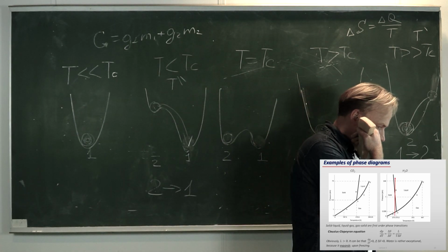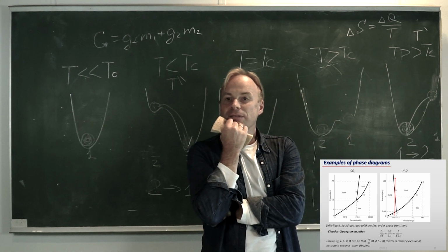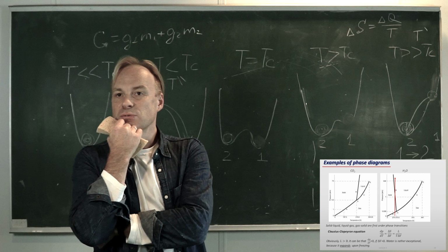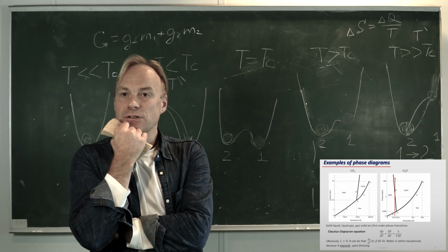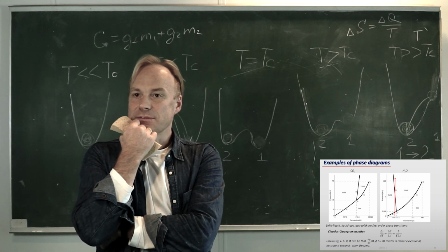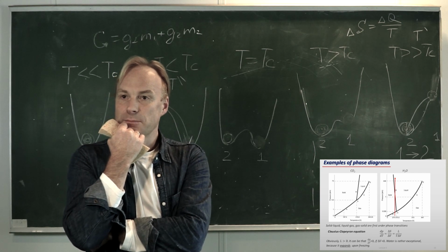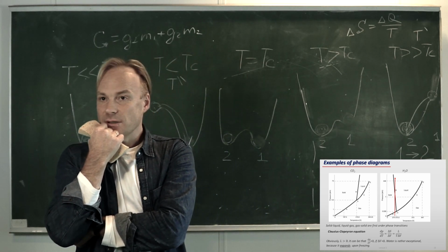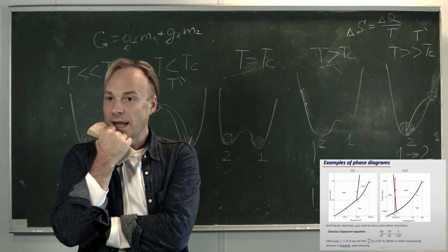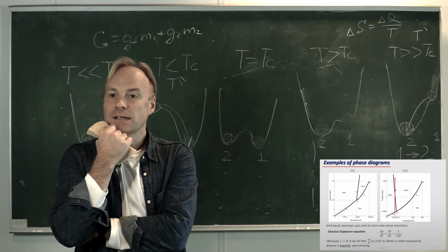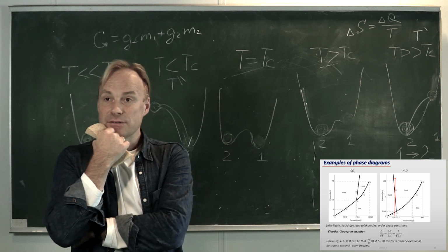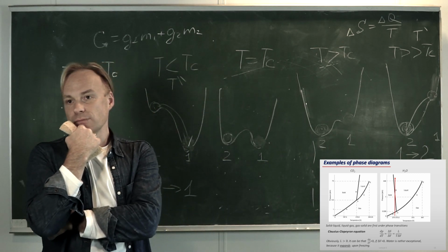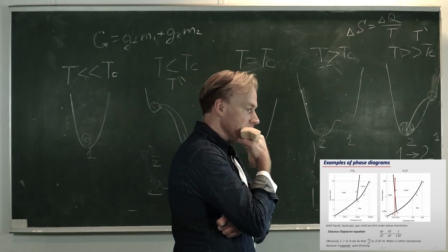So let's look at the Clapeyron equation and another very nice feature of this phase diagram, in particular the line that separates solid phase and liquid phase for the case of water. Obviously, in contrast to the phase diagram for CO2 gas, we can notice a negative derivative of pressure with respect to temperature for this line. It means that if you increase temperature and promote the transition from solid phase to liquid phase, you will have to provide heat, and the heat is positive, but it will also mean that the change of volume is negative. So upon transition from solid phase to liquid phase, water decreases in volume. Another way around, if you freeze water, it will increase in volume.